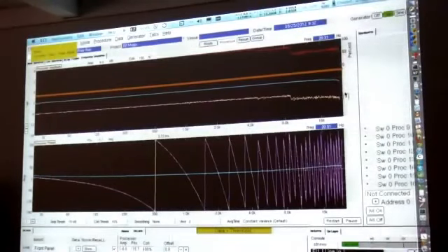And what is the maximum cancellation? 1 minus 0.5 is 0.5. So the maximum cancellation is minus 6. Exactly here we will have summation, exactly here attenuation. We start with summation. So the whole graph will be contained in this orange rectangle.